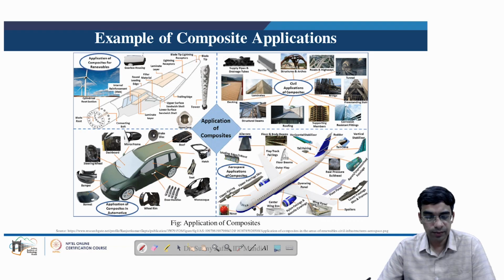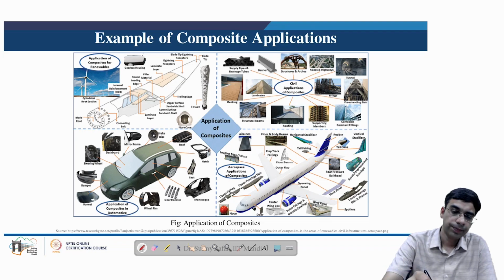So we can see the summary of all the applications of the composite materials, which are known for their high strength and less weight. Given this unique property, because if we talk of metals, they have very high weight because of their high density. And if we talk of ceramics, they may not be able to have sufficient stiffness under these varying wind loads. So polymer based composites are basically the choice of material for the wind turbine.